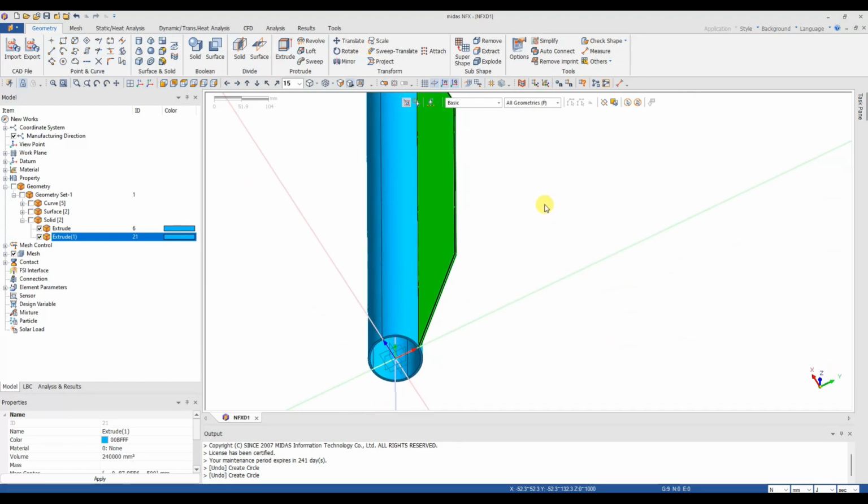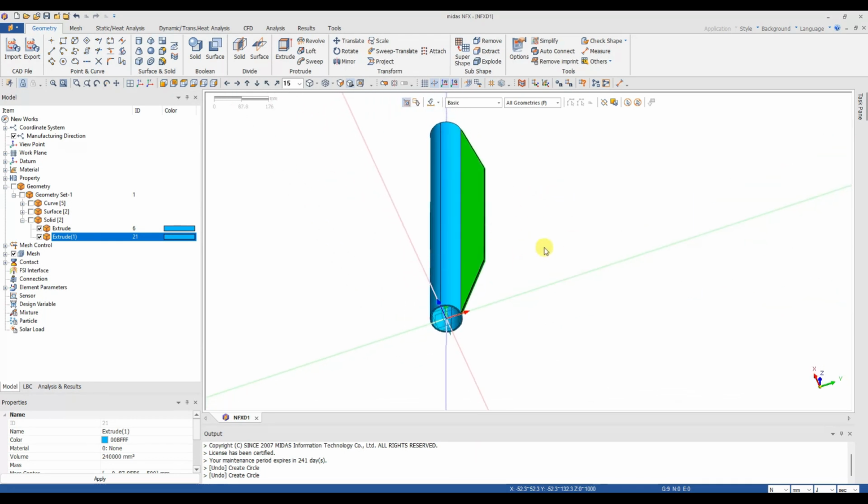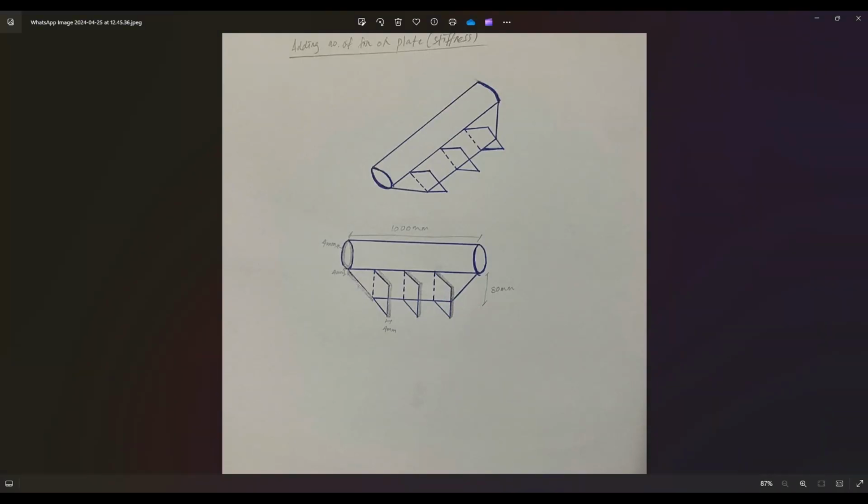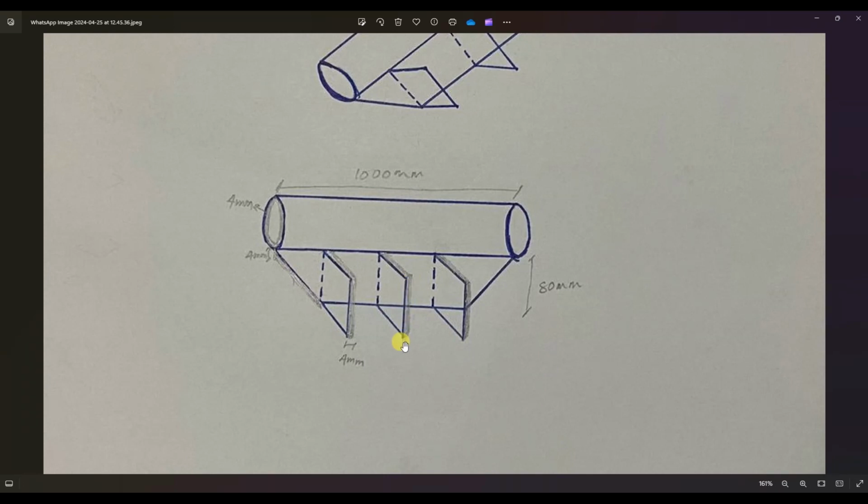All right. So we are going to do the attachment from this solid to another solid by using two different methods. One is Boolean and one is creating the contact. But before doing the contact or the Boolean, we will try to finish all the model. We're going to create a square plate over here. I assume that this square plate is going to have 80 mm on each edge with a thickness of 4 mm. I'm going to assume that this plate sits in the middle of the cylindrical, whereas the other two will sit at the edge of this trapezium.